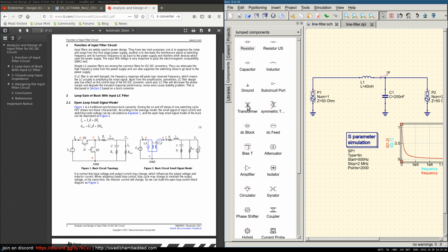And I can also try to eliminate as much as possible the expected interference. For example, I can slow down the edges of any serial signals. Make them a little bit smoother without degrading the data rates. If I have something with a slow data rate, I can filter the edges so that they are much smoother, and the transmission can still continue as it should.